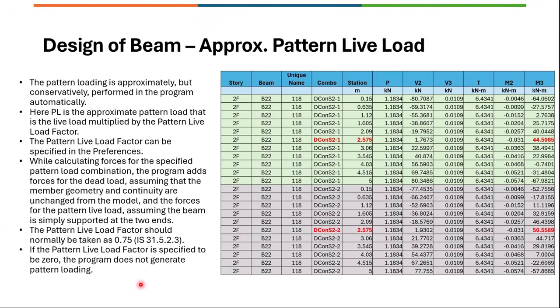The other one related to the beam design would be the pattern live load. The program performs an approximate conservative pattern live load. Because pattern live load is a complex analysis, we have to do it on the floor slabs on each panel, arrangements, etc. So that is also possible within the program, but you will have to take control of those arrangements, and it can also be done in an automated fashion. The program can handle it. But as far as a simple design is concerned, the program internally does this conservative and approximate pattern live load.